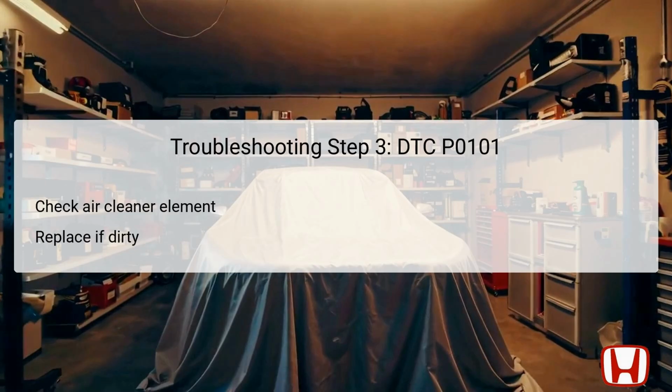In this step, you will inspect the air cleaner element. A dirty or clogged air filter can severely affect airflow into the engine, leading to inaccurate readings from the MAF sensor.